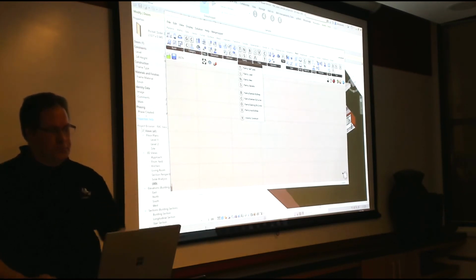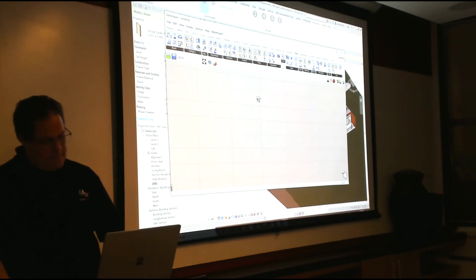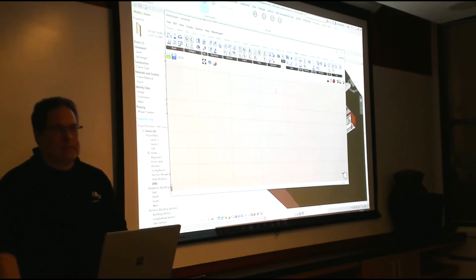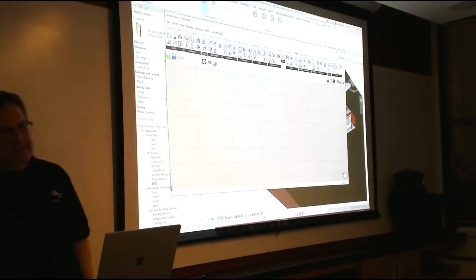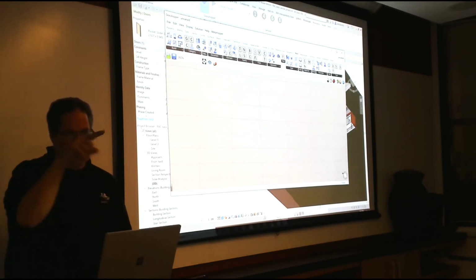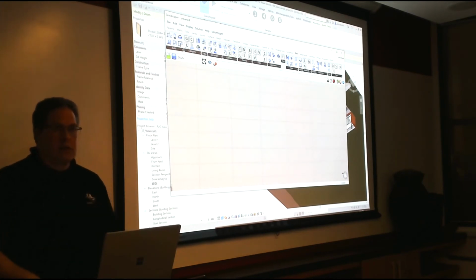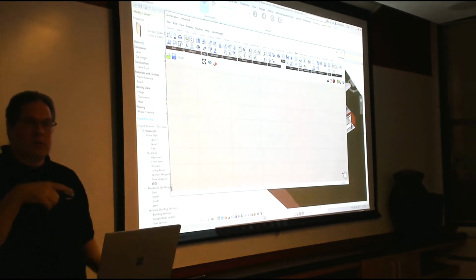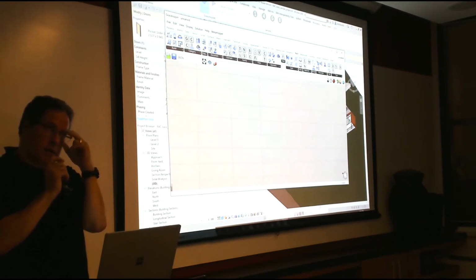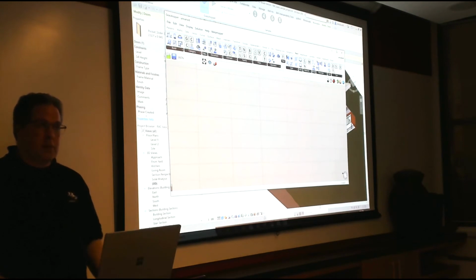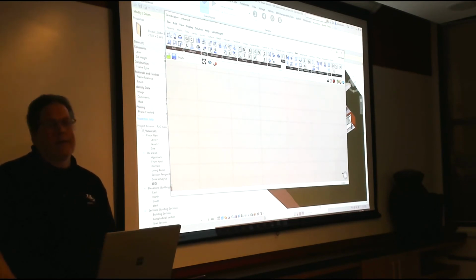So for the adaptive component workflow, are you creating the adaptive components in Revit, or are you making them in Rhino? In Revit. In Revit, okay. And then it just finds the family type and pushes it. Then you send your points in the correct order, and off it goes. And you can set parameters. If you have parameters in there by name in the adaptive component, you can set those with Grasshopper on the fly too, like mullion depth and all that kind of stuff.